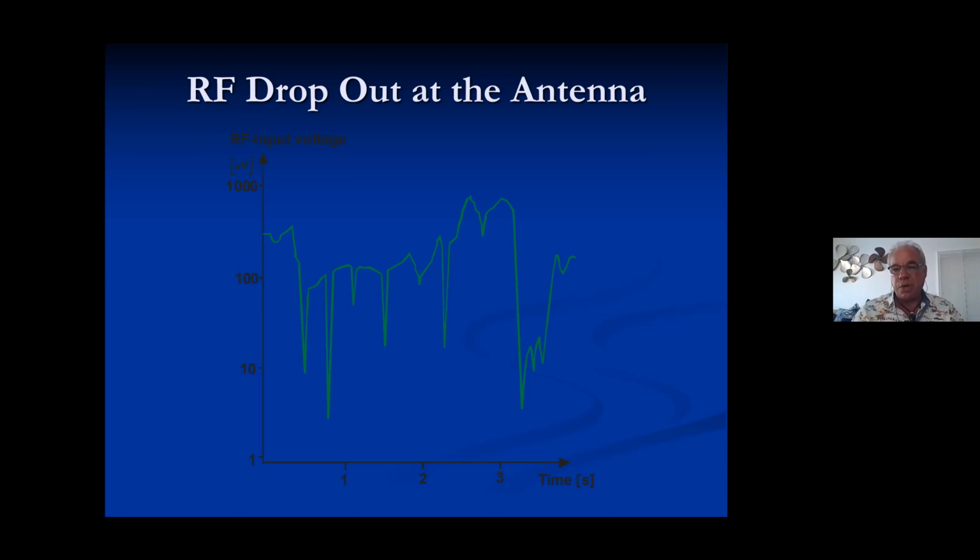I generally squelch my analog systems down to about 2 microvolts, or right above the RF noise floor, whatever it may be for the room. In this case, if I were setting the squelch, those dips may not cause a dropout. If you were one to set your squelch a little higher for some reason, or your noise floor was high and you had to set your squelch higher, then you'd have a couple of dropouts, probably those bottom 2 or 3 dips that go below 10 microvolts.